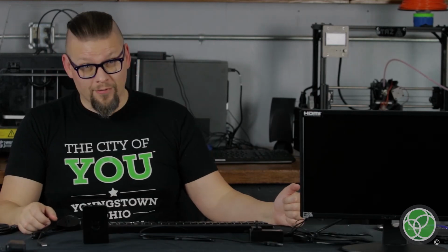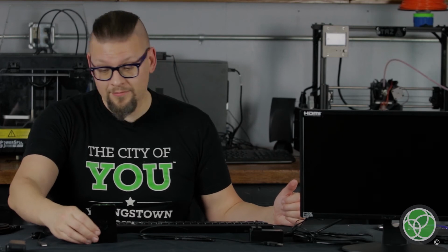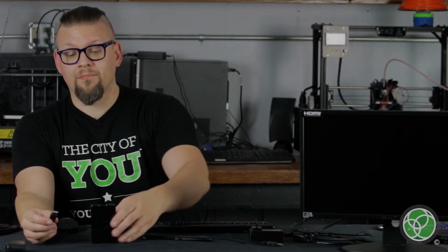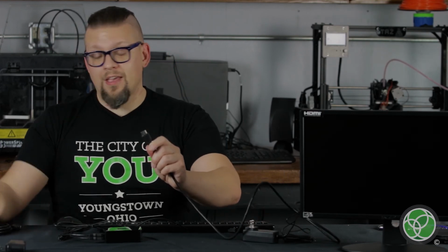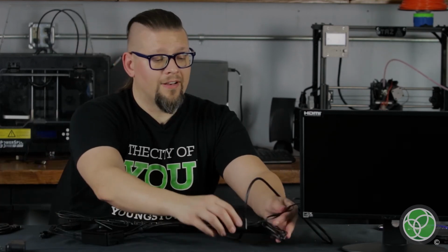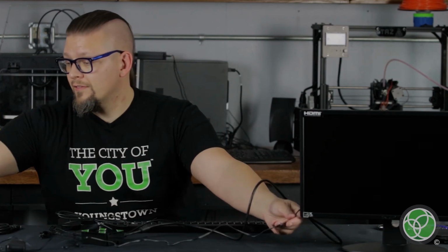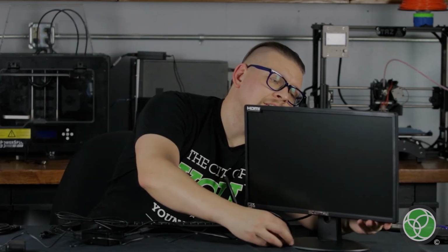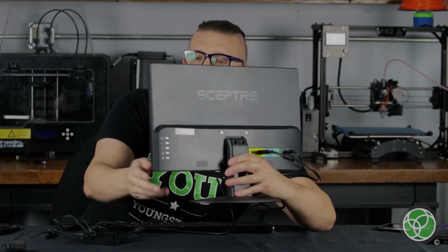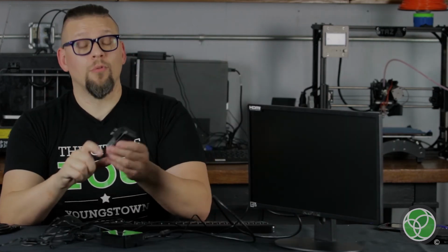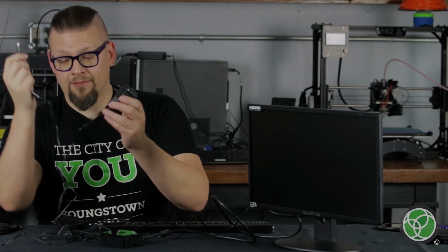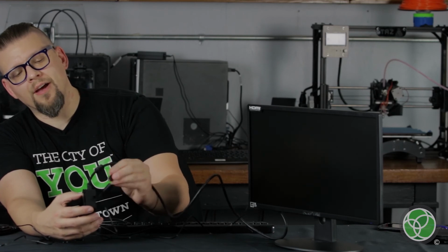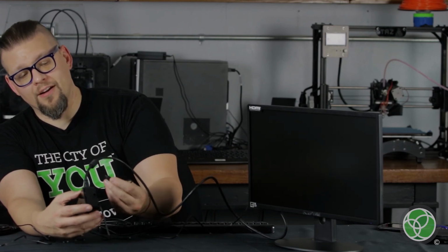Next, we're going to plug the peripherals into our Raspberry Pi computer so that we can boot it up. Next, we have the other side of the HDMI cable. We'll go ahead and plug our monitor in. The power button is on the back side, right here. Last, we'll plug in the Raspberry Pi power connector that ends with a micro USB. There's only one right way to put the connector in. If you look carefully, the larger end is on the top.